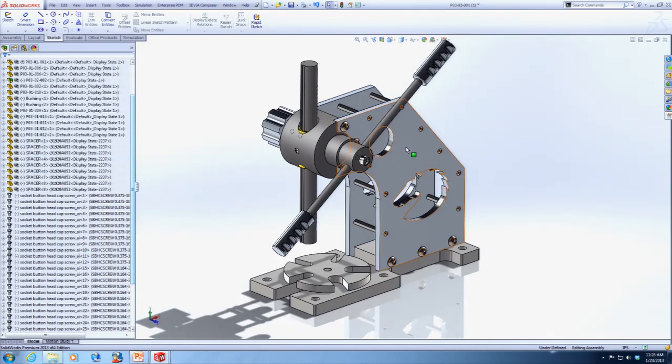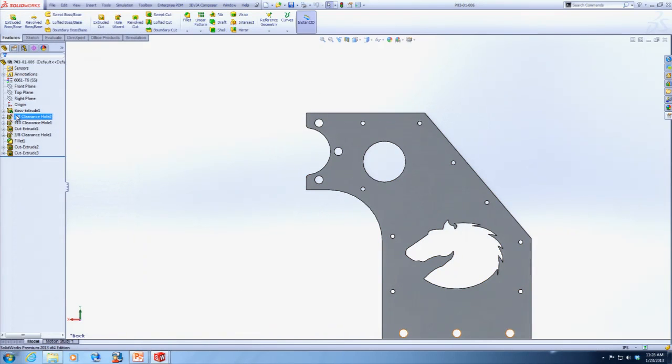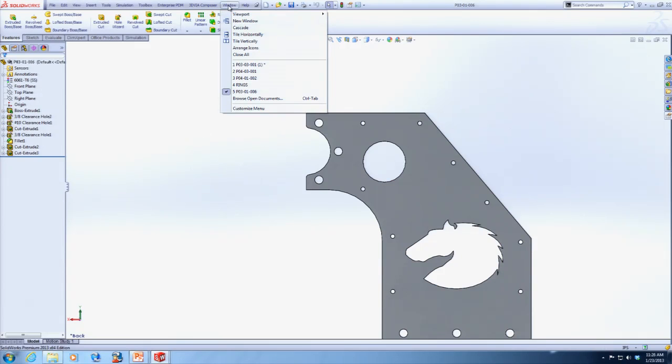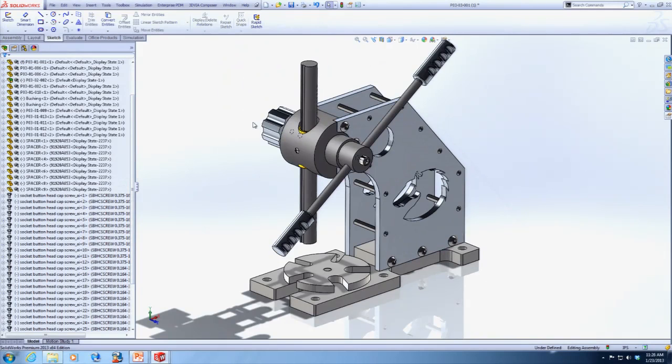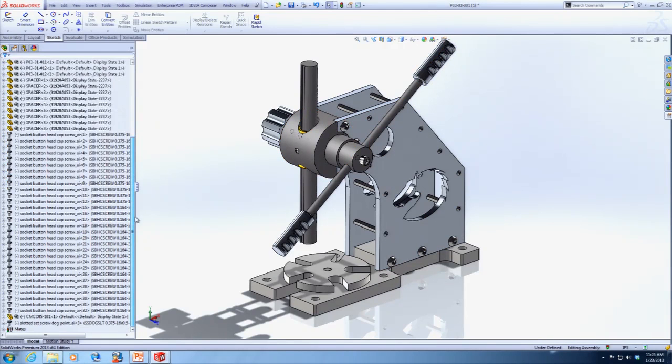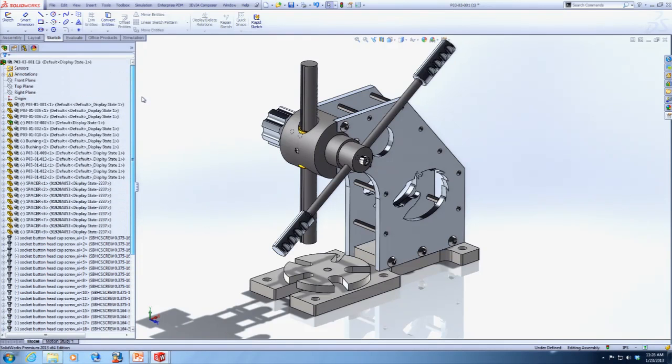Okay. Yeah, because through Hole Wizard you can get the clearance holes. So then you don't use feature-driven component patterns in assembly? Yeah, that has been done once those come in. Yes. I mean, from a production standpoint, having the number counts automatically put in versus them sitting over there and mating up each tiny little screw makes things simpler.